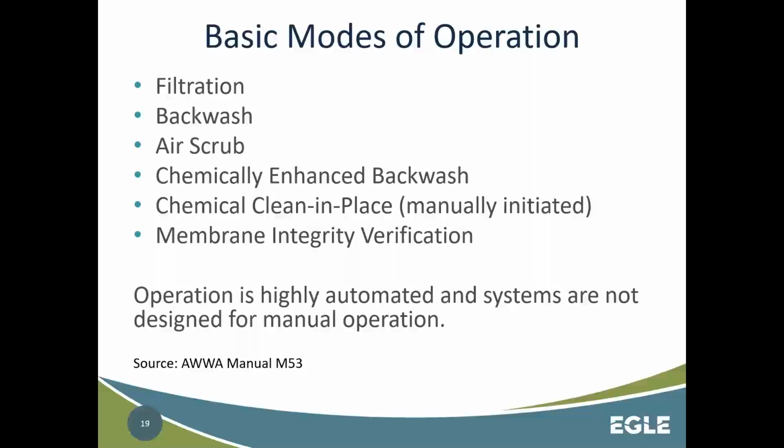So I would point out that these systems are operationally complex, requiring simultaneous monitoring and control of many inputs and outputs. Most of them are based on a PLC with a SCADA interface, and the complexity and the timing of all the valve sequencing makes it pretty impractical to operate these manually.